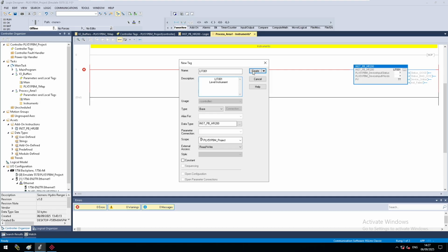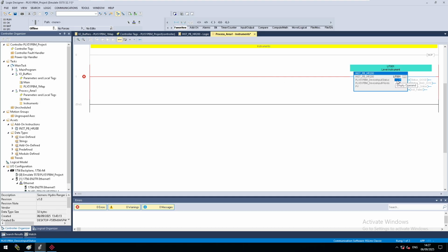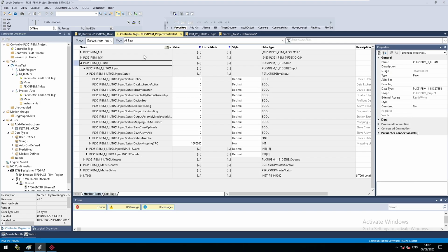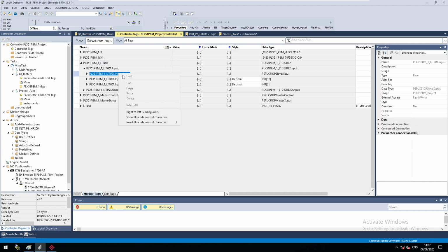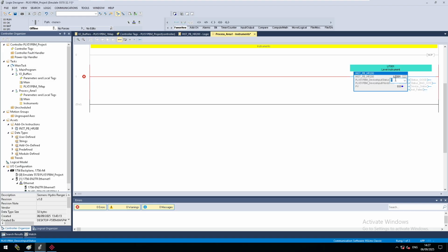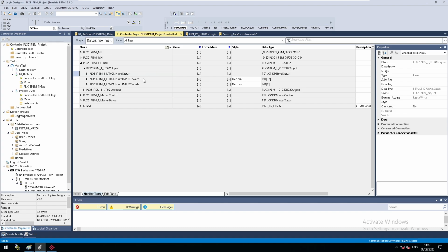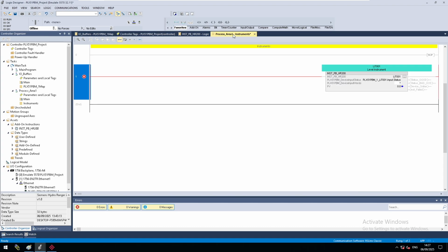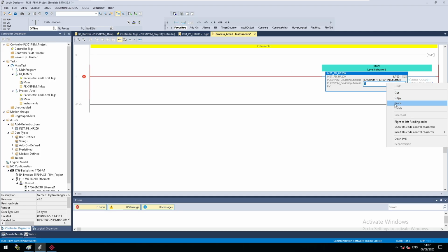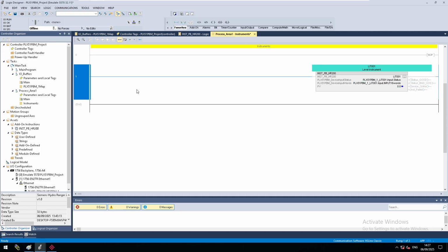and click create. So now I'm going to want to put in my device input status, which is from the PLX51 module. So I'm just going to copy that. And I can paste that directly in now. And the next bit it wants is our device input words, so that's our 16 words. I'm going to ignore the 2 words for now for the totalizer. And then I'm going to paste that in. And that's all healthy now and ready to be used, and then click save.